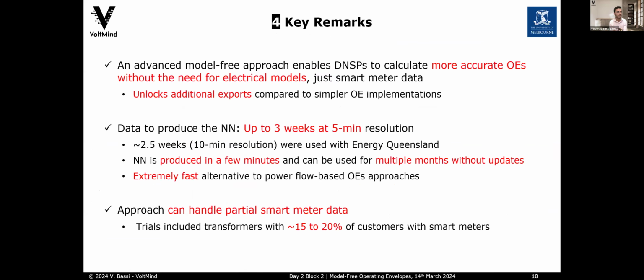As key remarks for this presentation, well, first, we can say that an advanced model-free approach enables DNSPs to calculate more accurate operating envelopes without the need for electrical models, just smart meter data. What we have shown here is that our approach can help to unlock additional exports compared to simpler DOE implementations.